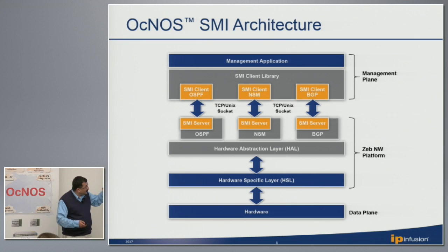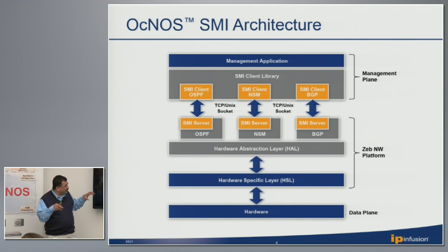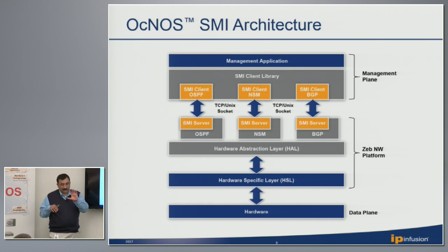That's what gives us the flexibility to add protocols very quickly. Even for managing the chassis, the same thing applies. We have something called a CMMD module. Depending upon what kind of device it is, it could be an I2C device, like a power supply, for instance. Even if it's a different power supply, we normalize it, because there's a protocol daemon for it. Fan control, LED, those kinds of things.